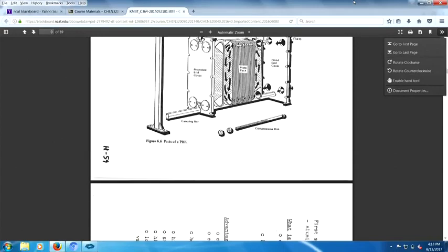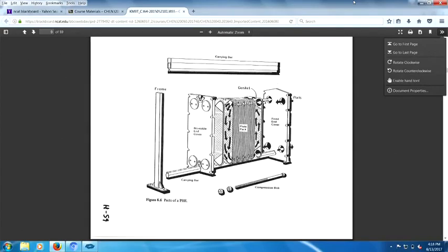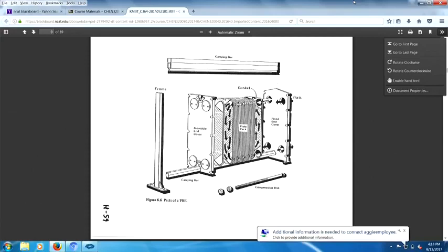I personally would not buy one of these things, save my life. I have no respect for this heat exchanger. If you never have to open it, never have to clean it, it's wonderful. Go ahead and buy it. If you're going to have to clean it once every 10 years, go ahead and buy it. It'd be great. But if you got to clean your heat exchanger every 6 months, it's a dangerous purchase.